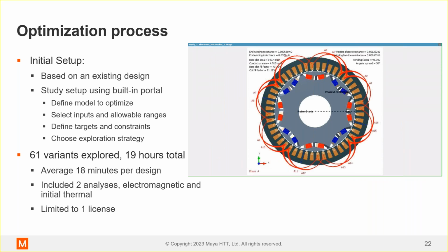So here, as we watched the number of designs, you can see that HEEDS was playing a lot with different shapes, particularly in the magnets and the cavities, bending things. You can see across the top as the different winding phase resistances changed, because geometry is changing around the end windings, and how the magnets started to change things. By and large, we left the winding layouts to be the same so that we had one-to-one comparisons back and forth.